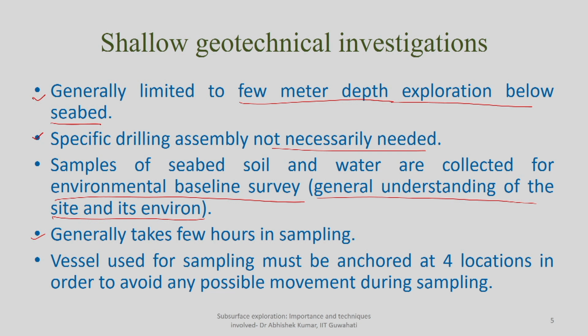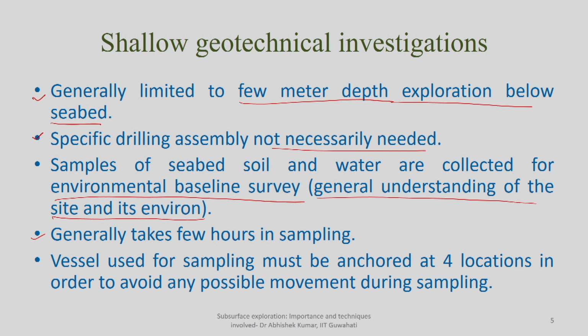As I mentioned, these kinds of investigations are more commonly practiced along the proposed route of a pipeline. You do the sampling, bring the sample to the laboratory, determine the strength characteristics, then go to the next site, which may be a few hundred meters away from the previous location, and so on throughout the pipeline alignment. So, it is generally used for that kind of investigation.